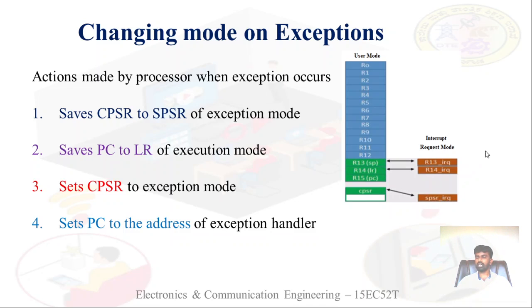If it is FIQ, how is it indicated? SPSR_FIQ, a short abbreviation of that particular mode. The present status of the CPSR should be saved to the SPSR of that mode. In this case, the CPSR of user mode is saved into the SPSR of IRQ mode.